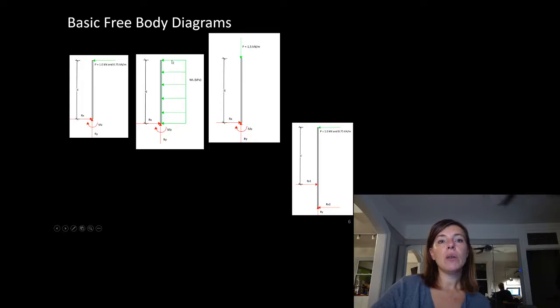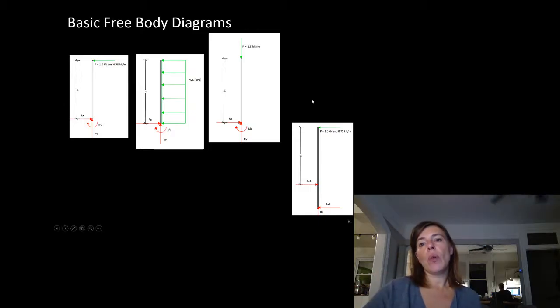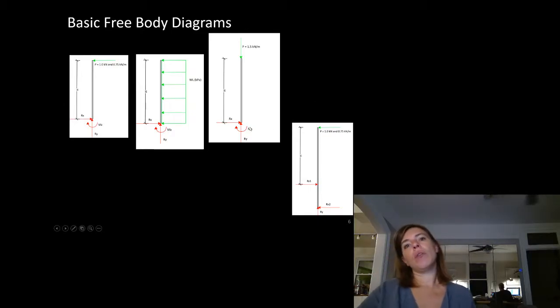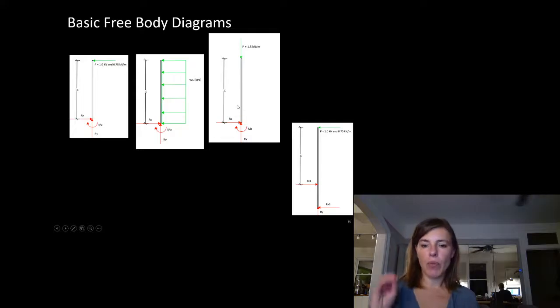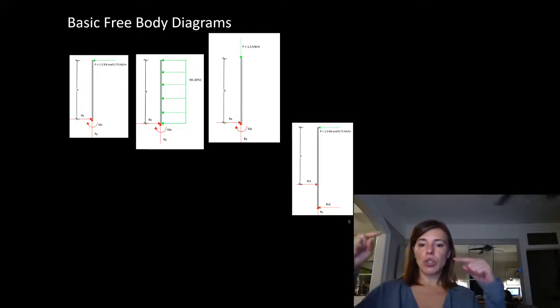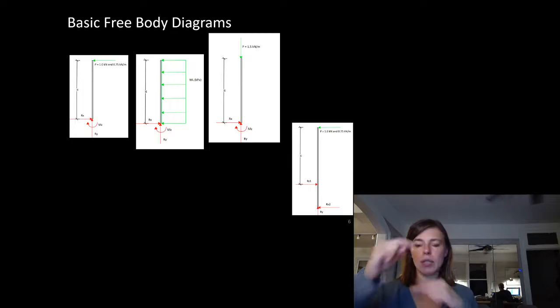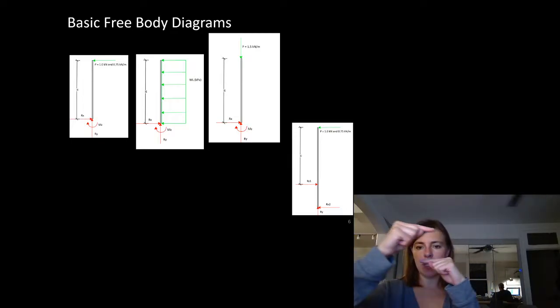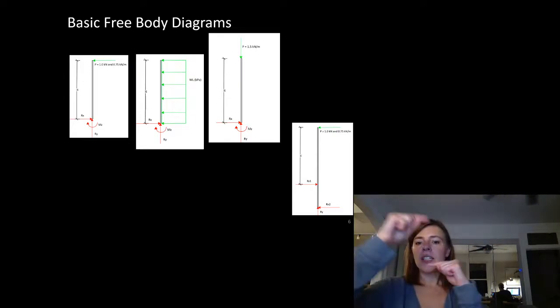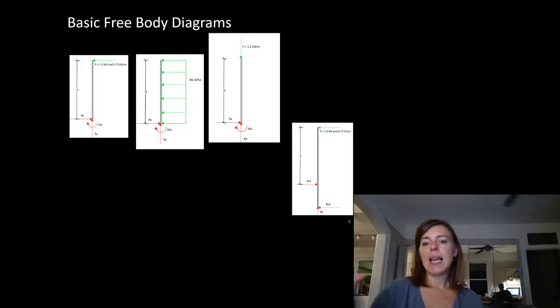Here it is with a wind load. Same free body diagram is applicable. Point load downward, same free body diagram is applicable. We could do a different way to resolve this moment. If you remember force couples, where 2 forces in opposite directions, equal and opposite forces, the same distance away from a centroid, or with different distances, can be the equivalent of a moment.